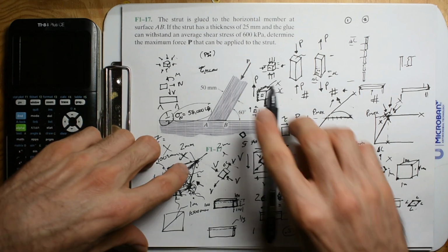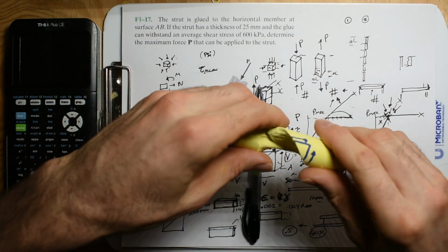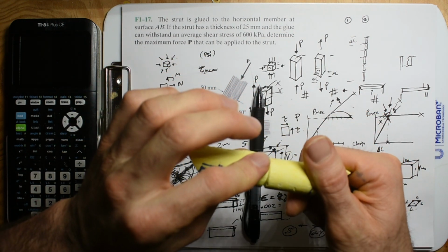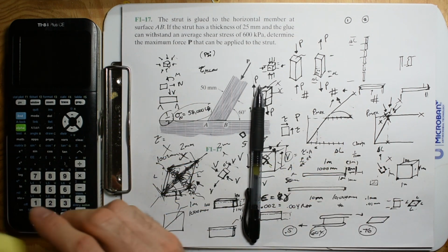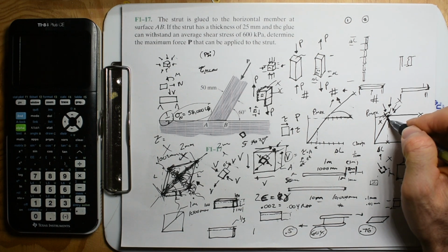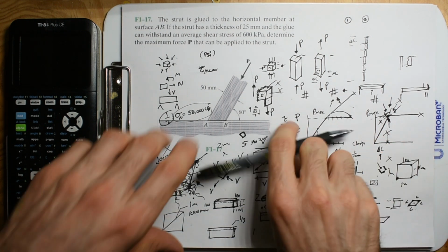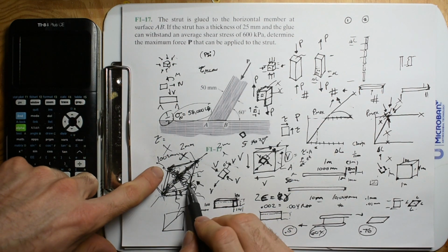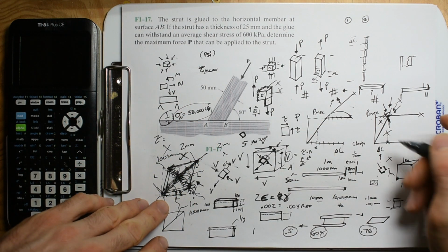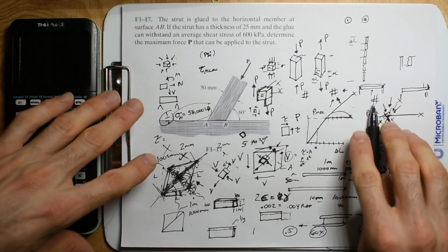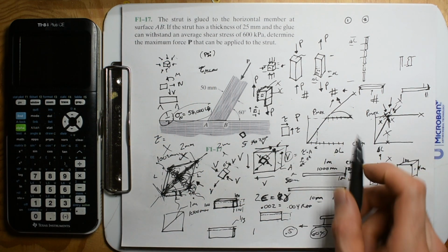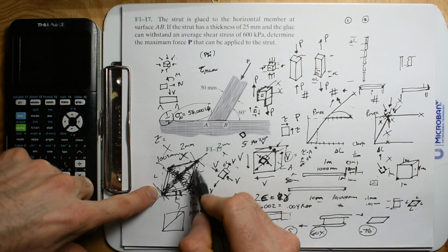What you see is that you can just keep turning this, and then you get a break like this. These will just keep turning, and then you'll separate, and you'll have flat ends, flatter than this helical shape. But this proportional limit, or yield stress, still applies. If you put more force than those loads we talked about, things will permanently deform, and that may be where people's lives are lost. You can lose your job. So you want to size less than that, and those limits are based on this change in shape.